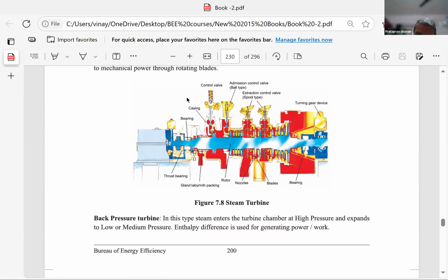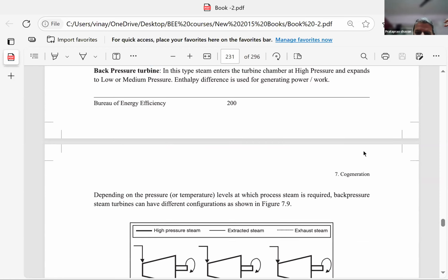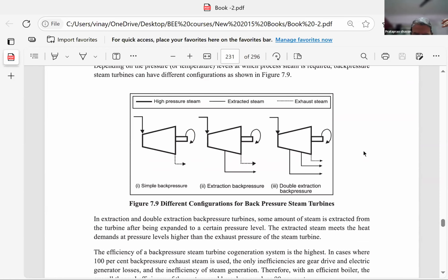Lastly, if the steam volume is much more, so that after fulfilling the process requirement the steam is still surplus, then that steam is allowed to expand till the last and then condense in a condenser, thereby increasing the electrical load output. Right? This we have seen: condensing, non-condensing, extraction steams like this. Here, the same is explained. The high pressure steam is entering here.